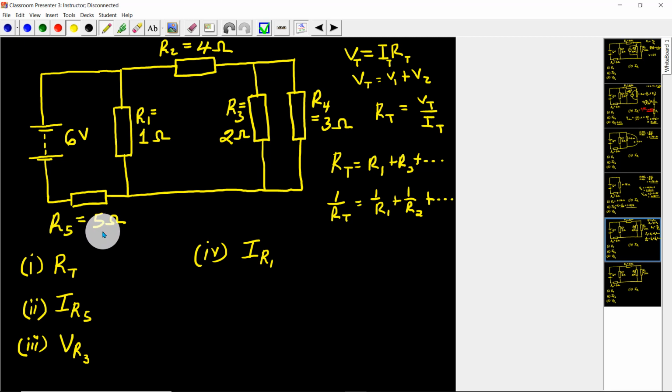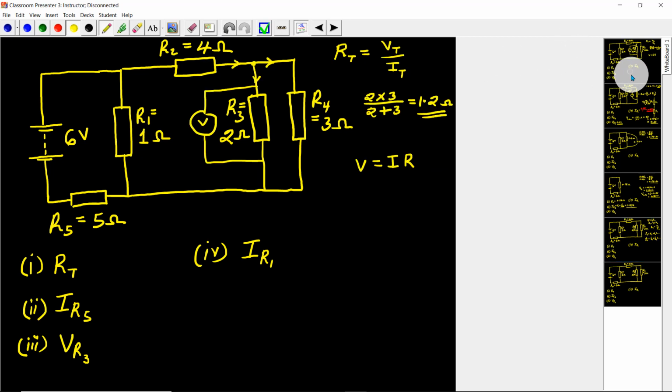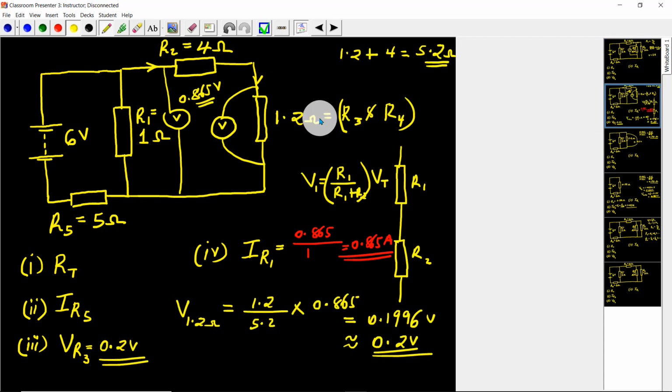It's always important that when you identify that smaller unit in the circuit, you ask yourself, if I use this equation on that unit, will it be affected by the other resistors at that particular moment? For this case, we found that it wasn't, because we were able to combine this and this to get one resistor which represents R3 and R4 directly.